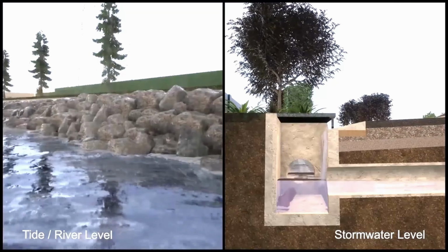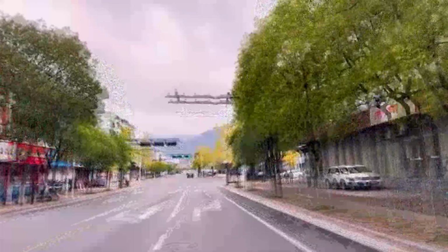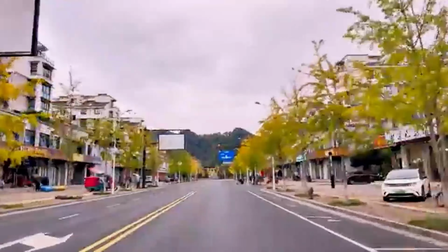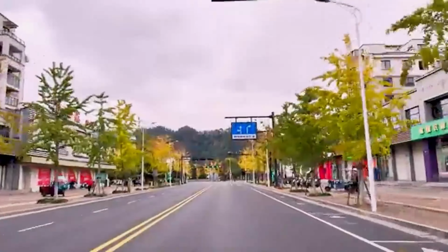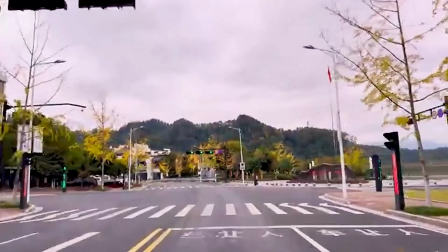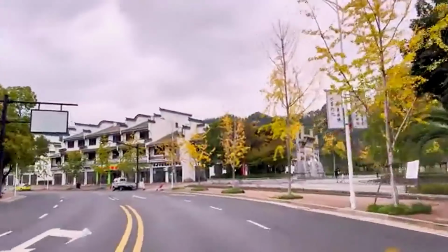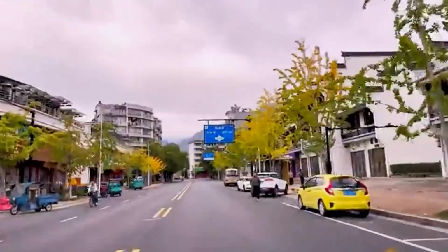Chapter 10. The human side of highway design. Modern highway engineering is not only about vehicles, it is also about human behavior. Drivers subconsciously expect roads to behave consistently. Sudden narrow lanes, unexpected curves, or confusing junctions can create panic and increase accident risk. Therefore, highway engineers try to maintain consistent geometry, predictable alignment, proper signs, smooth transitions, and clear visibility. This concept is called driver expectancy principle. Good highway design works with human psychology, not against it.